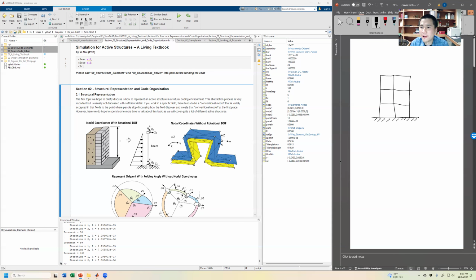And every node here, if it's 2D, should have an X, and then the Y, and then the rotational degrees of freedom, right? That's the abstraction we created, and all the members are beam elements, or columns, which are also beams essentially. So we just don't talk about it.